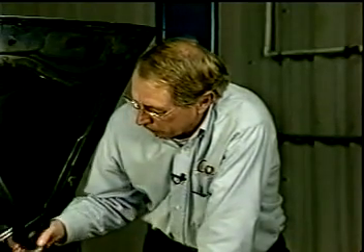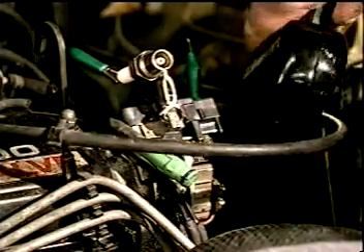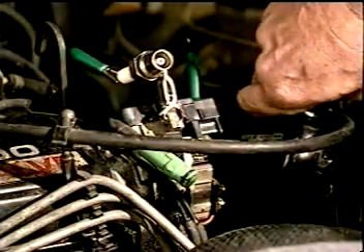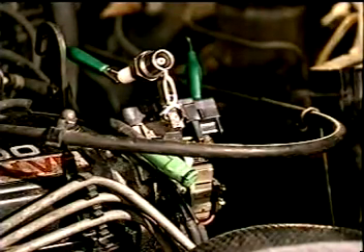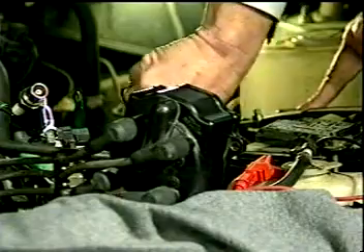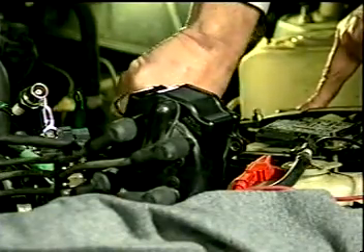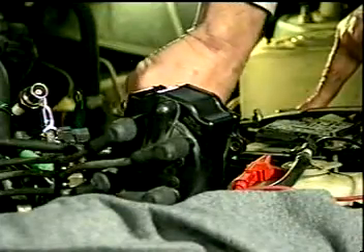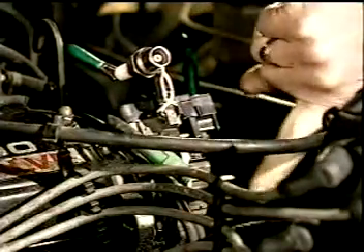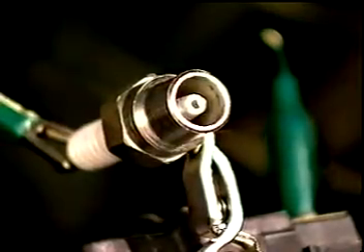If you focus on the spark tester, if I get that soldering iron very close to the igniter, notice the spark tester. So we know the coil and igniter are good. Okay, there's another way you can do it if you don't have a soldering gun. I could take one finger to the positive battery terminal, pick up some battery voltage, and take my other finger and bias the igniter with my body through the battery terminal.